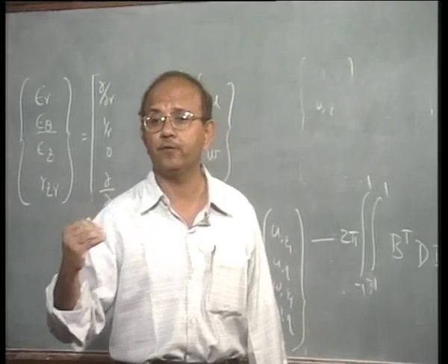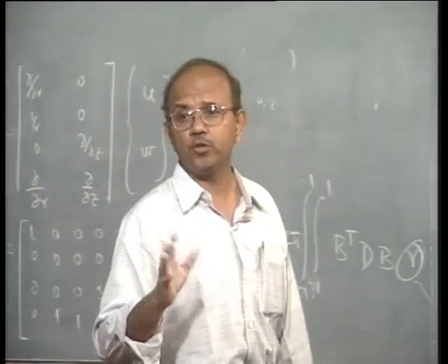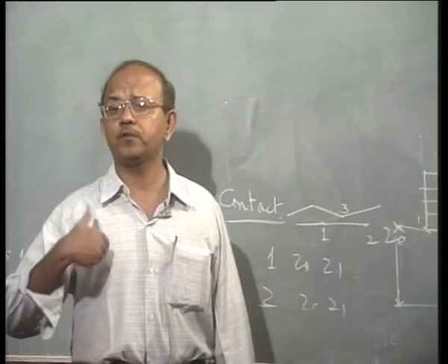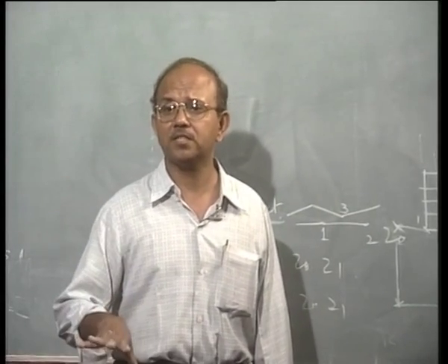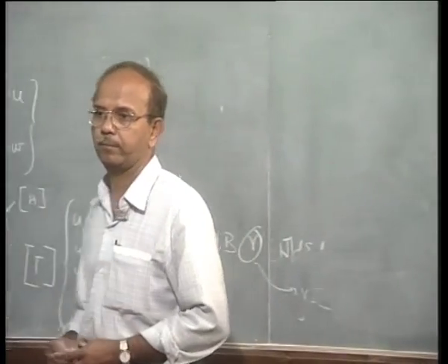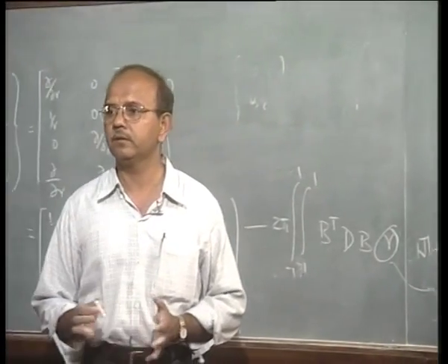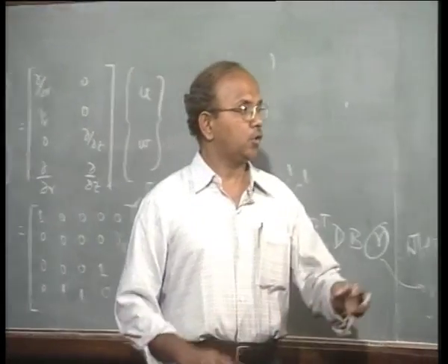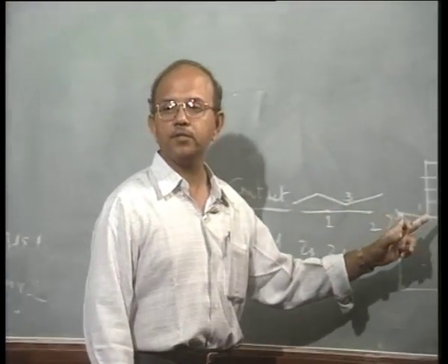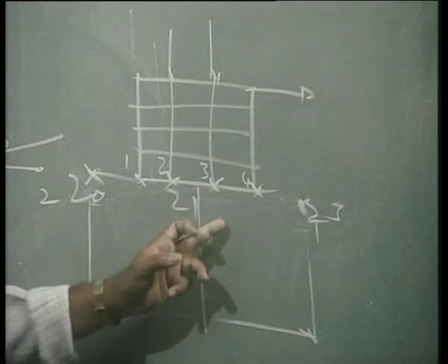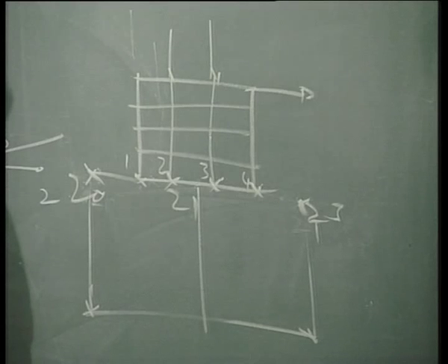You have to be very careful to define all the surfaces with which the master segment is likely to come into contact later during loading. Is it clear? Okay. So, the next step is for it to find out which segment it falls on, and so on.